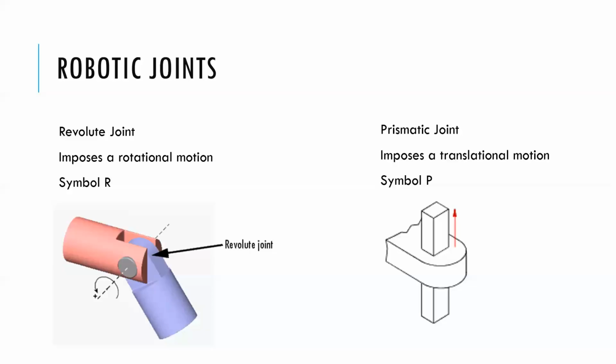So I'm going to start off with a review. This is what we covered last time, and we're only using revolute and prismatic joints there. There are also spherical ball motion joints available, not very common, but there are some systems that can do that. It's very hard to manufacture a ball joint versus a rotation. We're going to use an R for a rotation joint, and prismatic means you'll be able to translate there. You have a combination of R's and P's, rotation and prismatic, to make up a robot system.